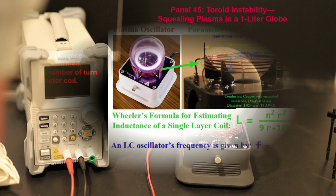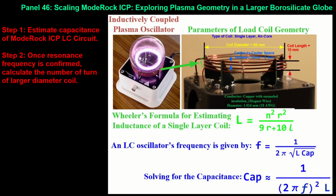The ModeRock device was redesigned to house a 2-liter borosilicate globe, doubling the original diameter. This modification enabled plasma formation studies on a larger scale, expanding beyond the previous 80 mm globe. To analyze the oscillator's resonance frequency, I estimated the inductance of the original 18-gauge air core coil using Wheeler's formula.